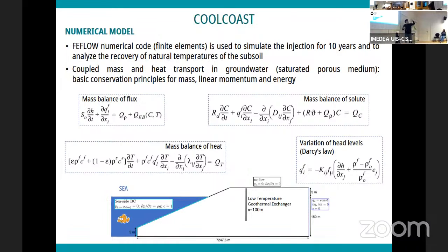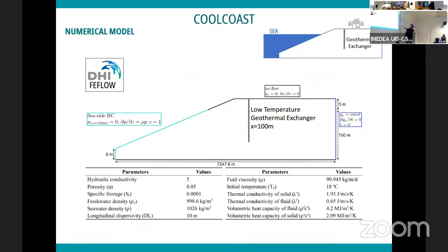It is a 2D model, indeed. It's like a slice that we cut of the aquifer until it arrives at the sea. Okay, there is the sea. This is the sea, more or less like this. In that place, on the left side of the model, I put a constant hydraulic pressure condition, a freshwater pressure, that is changed because of the density of the seawater. Okay, because of the environment. Using the density, we can equate the pressure from the freshwater to that of the seawater.